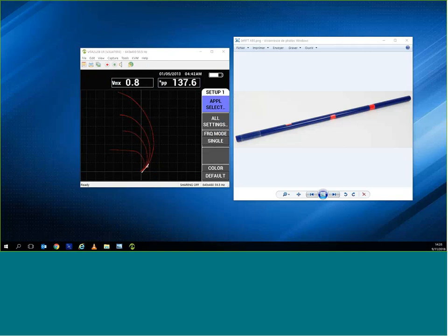I've calibrated all 3 defects on the right line, where they should be. So now I'm just pushing the probe back in. And at the end, I'm going to erase. And if we rescan, this one will be on 180 degrees, so it goes up to 180. The amplitude is always dependent on the material loss. So there you go, 180. The next one is 270, right on the line. The last one is 360, and very shallow.